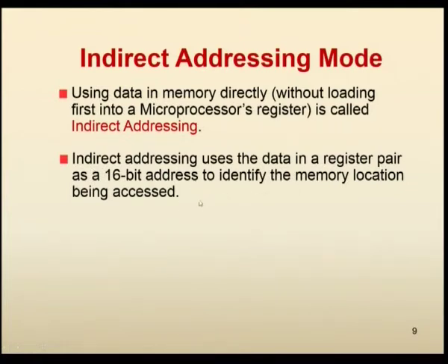We have register pairs BC, DE and HL. We simply use an instruction, and the instruction will automatically take the contents of one of the register pairs depending upon the instruction we give, and then the data will be transferred to the address pointed to by the 16-bit number stored in that register pair.